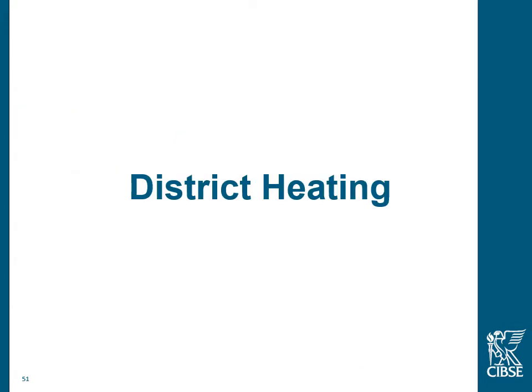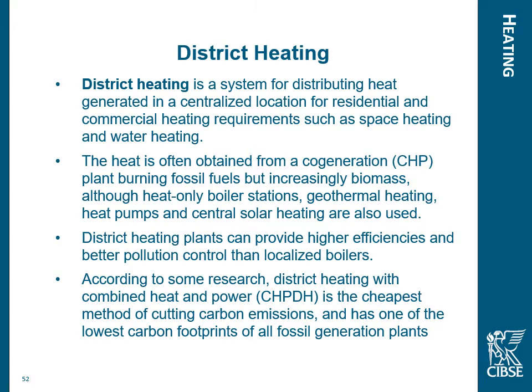Now, district heating has become quite popular over the last few years, heating networks as some people call them. District heating is a system for distributing heat generated from a centralized location for residential and commercial heating. Heat is often obtained from cogeneration, CHP. These are plants which actually generate electricity, and we use the rejected heat from them. According to some research, district heating with combined heat and power is the cheapest method of cutting carbon emissions and has one of the lowest carbon footprints.